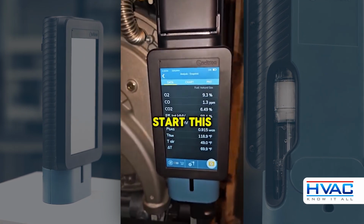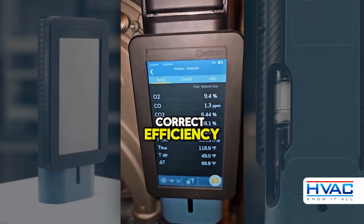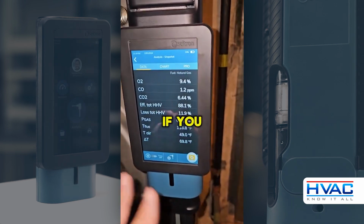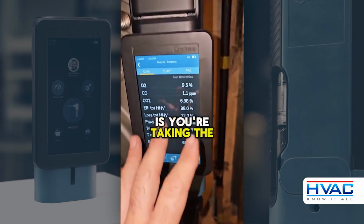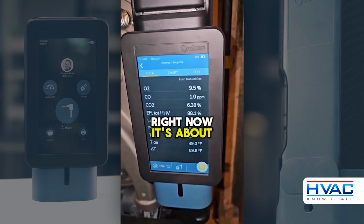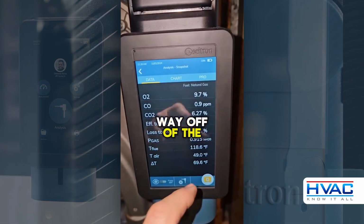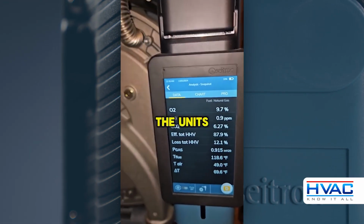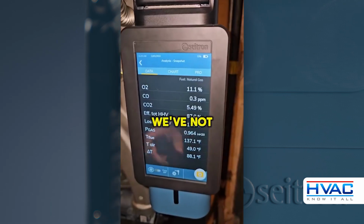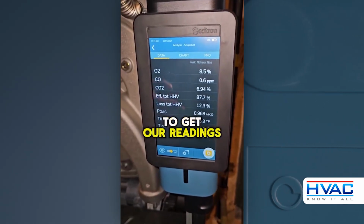So now we're going to start this thing up and take a reading. Now this is how you would get your correct efficiency. Otherwise, if you have it in the auto mode, all you're doing is taking the temperature directly from the unit. Now, in this room right now, it's about 74, 75 degrees. So way off of the actual air that the unit's going to be using for combustion. We've now been up and running for a bit, so I will hit the pump. Now we're going to start to get our readings coming in that our probe is seeing.